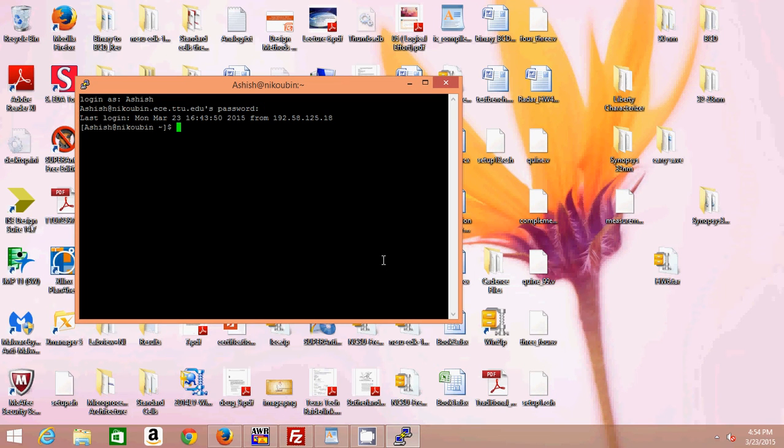Now before using the IC Compiler, make sure you have your Verilog code synthesized using Design Vision and have a netlist file and the SDC file, that is a Synopsys Design Constraint file. These two files are generated as the output of a Design Compiler.